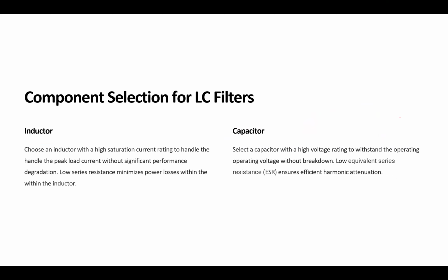If you want to choose an inductor, you want to make sure that it would not get saturated, and that it can handle the amount of current that you're supposed to provide at the output. Make sense? These are practical tips that you want to have in mind. So you want to choose an inductor that would not get saturated in your normal working.